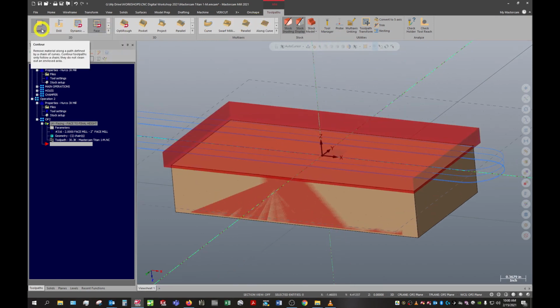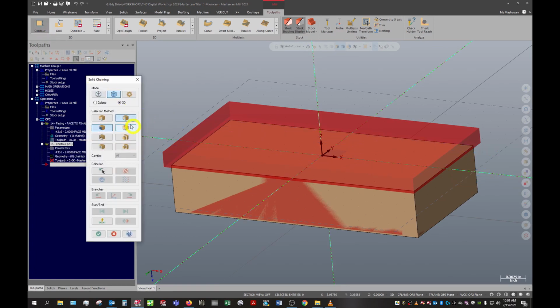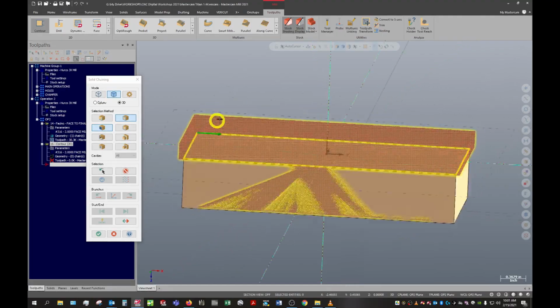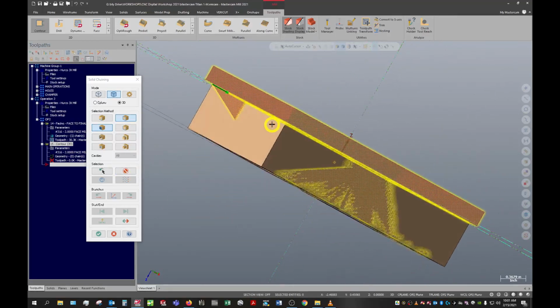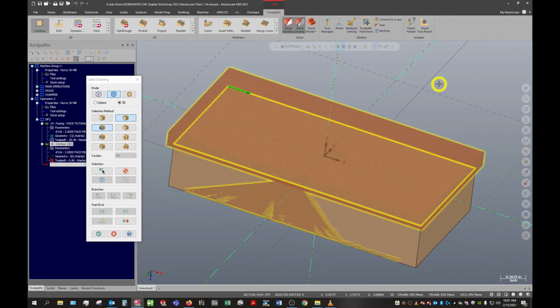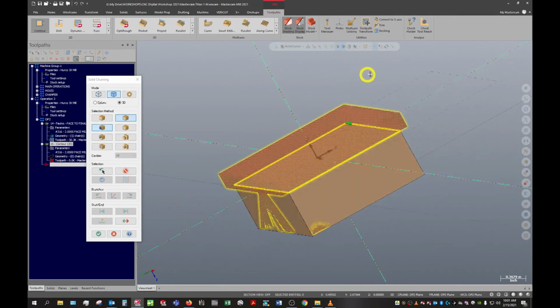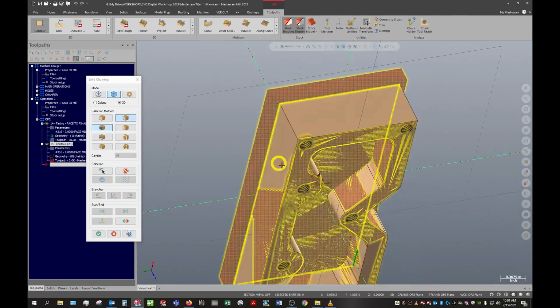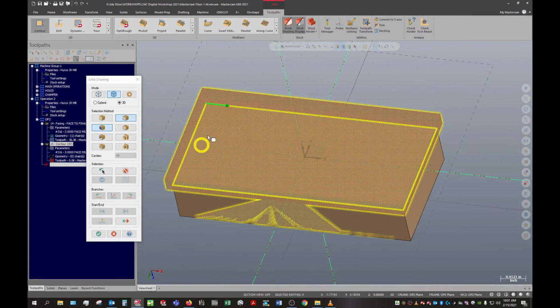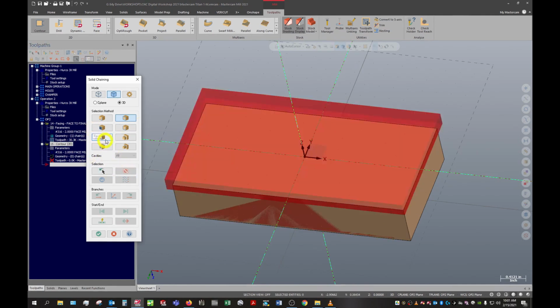Back in Toolpath, we'll do contour. Again, we want to be on chaining loop. You can leave face on. This allows you to select individual faces like this. Now when you do that though, it kind of creates a whole slew of issues, so I generally like to stay away from selecting faces because it just isn't super convenient many times. Sometimes there's an application for it, but for simple chaining like this, we want to avoid that, so I like to just turn off the facing option.